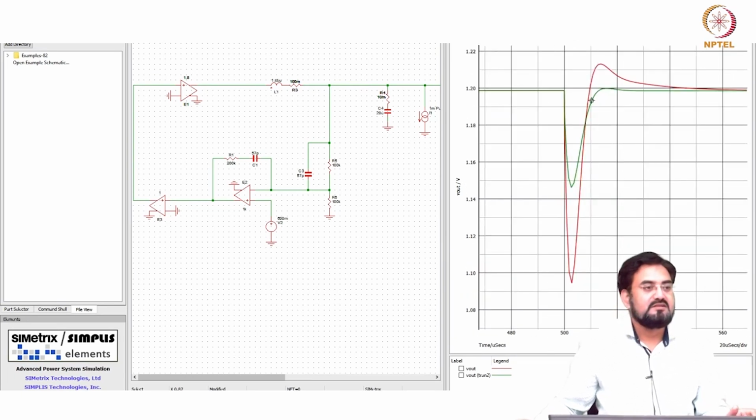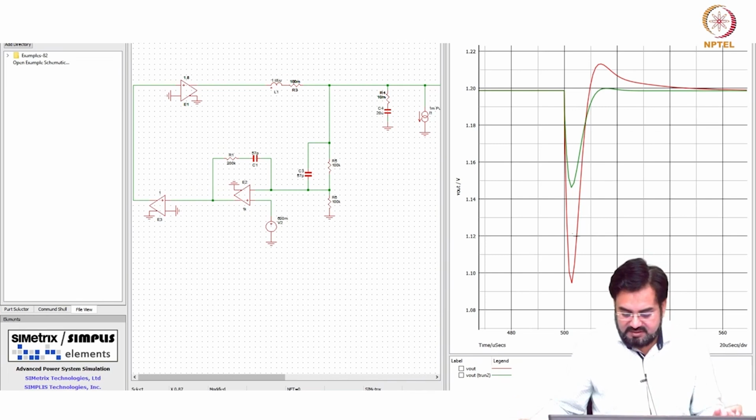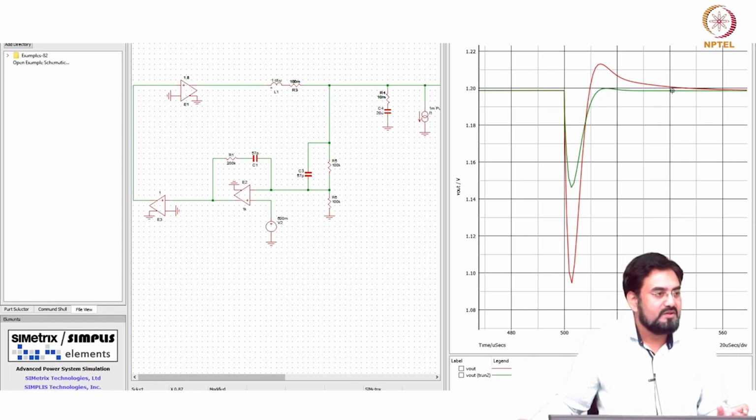Huge benefit, huh? Simply by changing L and C. So, we already know that you have a square effect because your slew rate is getting faster in the inductor and you are adding more cap. So, it won't discharge that much. So, that is why just by simply changing the L and C values, it is reduced by, I mean, almost half, more than half actually, and your overshoot which you were getting due to that resonance peaking, that also almost goes away.